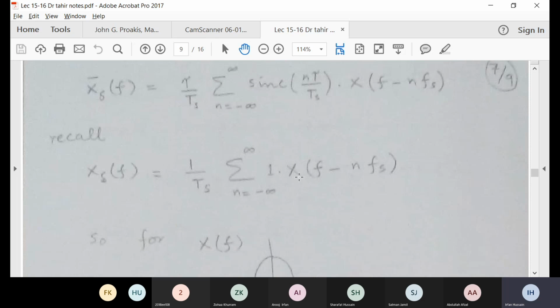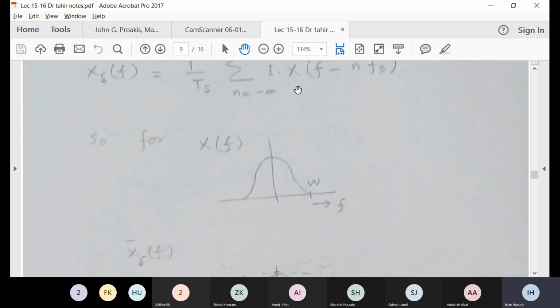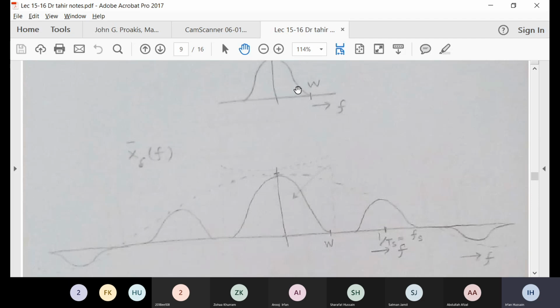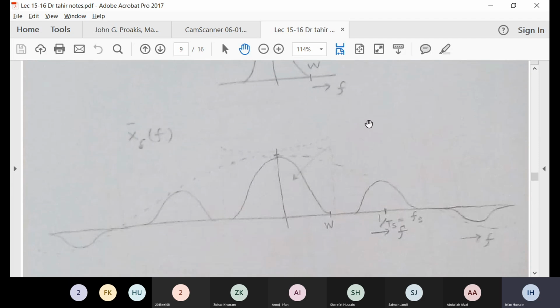So this means that if we have this pictorial representation for theoretical sampling, you can see that the spectrum is shifted after every fs, so there is a train of spectrums at every fs, representing the sampling operation in time. So this train is being modified by a sinc function. So if this was our fs previously, you could see that yes, fs was being repeated, but they were all of the same height. Now what has happened is that there is an envelope corresponding to a sinc. So all these replicas are there, but they are being modified with the overall sinc function.